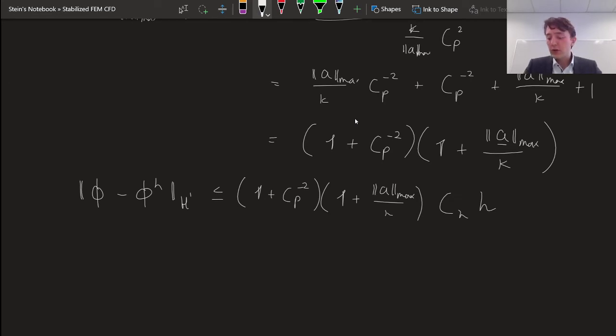So once we start to reduce our mesh size, h, well, all the other expressions are independent of our mesh. That's kind of the objective that we always have with the analysis of convergence. We want to get some constant expression that is independent of the exact choice of mesh and multiplied by our mesh size, h. So if we reduce our mesh size, then we can anticipate that that constant remains constant, and our error reduces by the fraction that we are iteratively reducing our mesh size with.